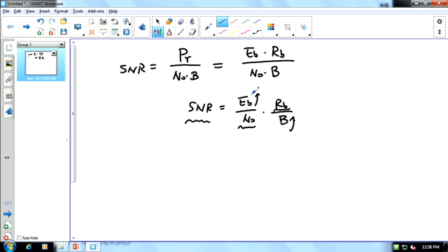Previously, we were just transmitting 1 bit of information with an uncoded system. Now, for example, if we have a code rate of 1 over 2, we are using 2 bits to deliver the information of 1 bit. So the total energy for 1 information bit is the combined energy of the information bit and the redundancy bits.